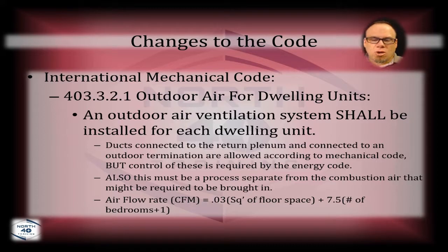So when the fan's running, it's drawing air through the return air, which by default is going to draw air through that fresh air exchange. That's been done for decades. Hey, there are some inherent problems in that, and many municipalities no longer accept that.